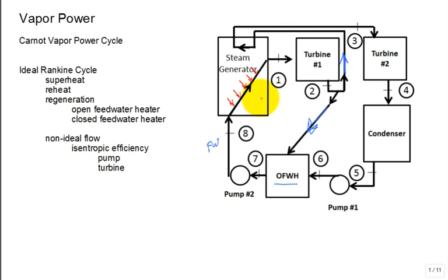Okay? We talked about what is the symbol Y. Y is a mass fraction, true? It's a mass fraction, so it's the mass flow rate that goes down to feed the open feed water heater divided by the mass flow rate that came through the first turbine stage. And so it may be 20%, 30%, something. Often it's less than 50%. Let's say Y is 25%.